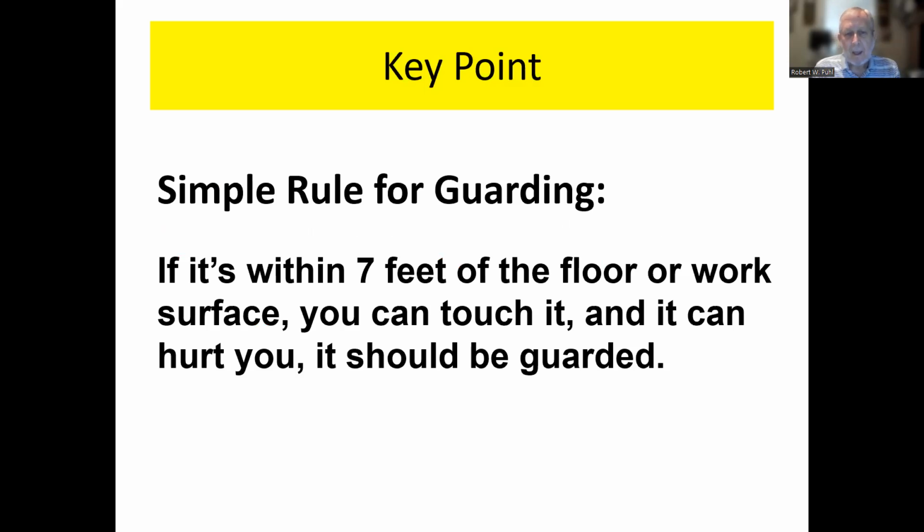Trust me. Here's my simple rule for guarding. If it's within 7 feet of the floor or the work surface, you can touch it and it can hurt you, it should be guarded. Now, you won't find this exactly like this in OSHA regulation, but you will find the 7 feet. I think I had this printed on the back of my business card. And I would tell the plant managers, this is the rule for guarding. It's pretty simple. Within 7 feet of the floor or work surface, you can touch it and it can hurt you, guard it. Why wouldn't you do that? Regulation or no, why wouldn't you do that?